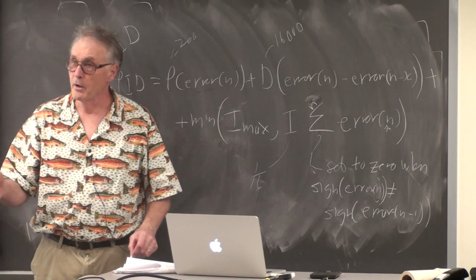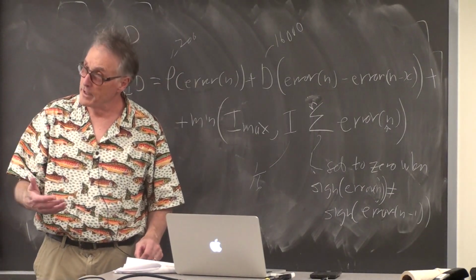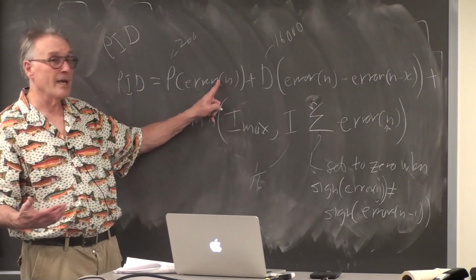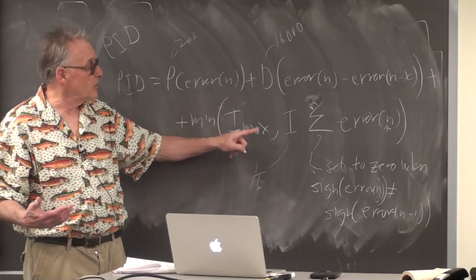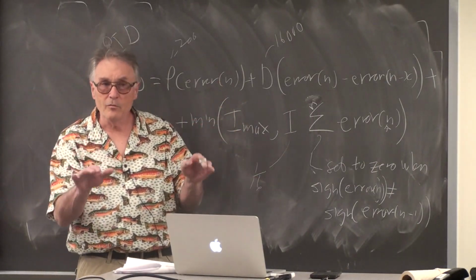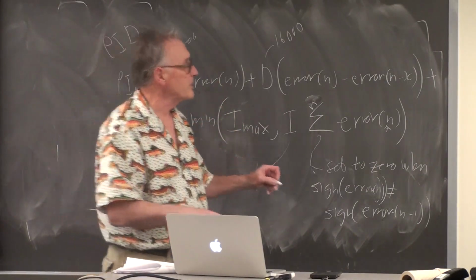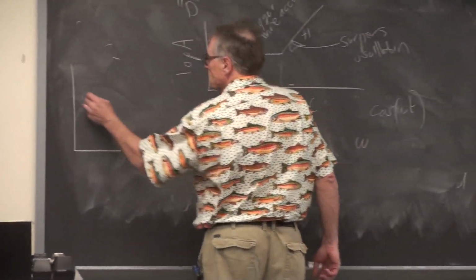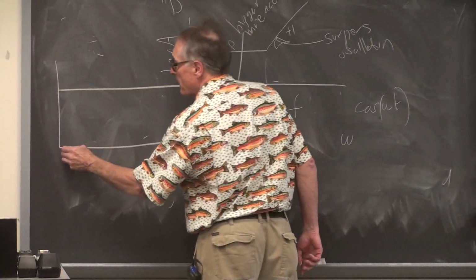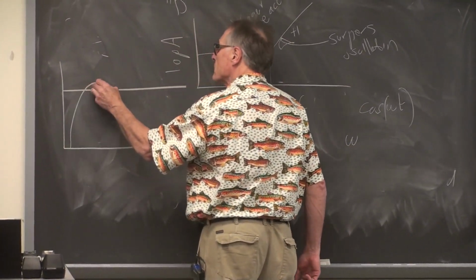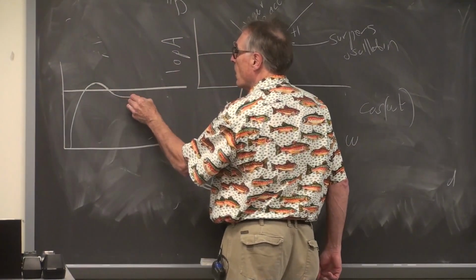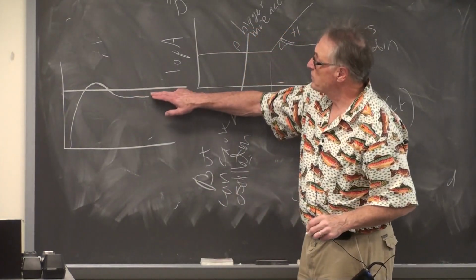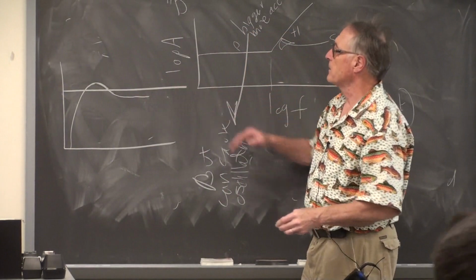The integral term, because it is a negative phase shift, will destabilize the system just like a high gain here. So you want to not destabilize the system too much, but if there's a static error, let's say this is the desired value, the system comes up, overshoots, you want it not to stay at a low level forever, just below the desired value.